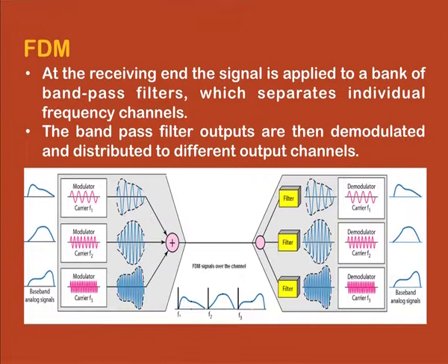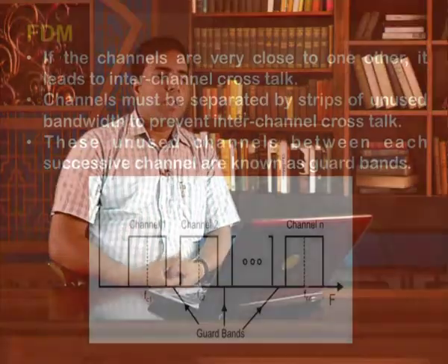to respectively f1, f2 and f3 center frequencies, and having a bandwidth which is equivalent to the transmitted signal bandwidth. And this way we can separate out the signals for respective destination from the common received signal at the receiver, and then it can be demodulated and fed to the different destinations.